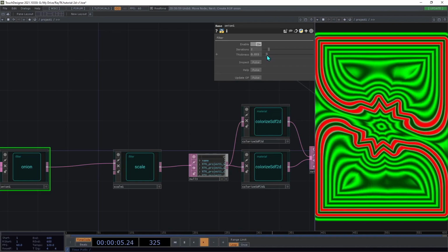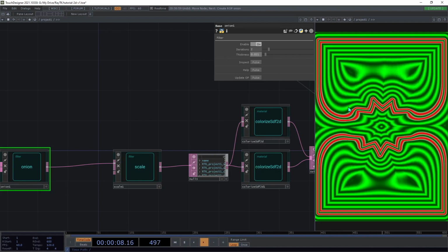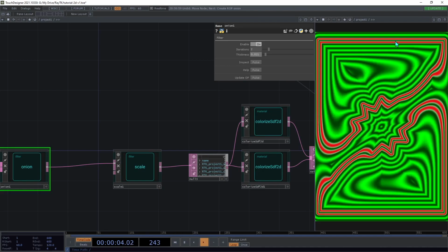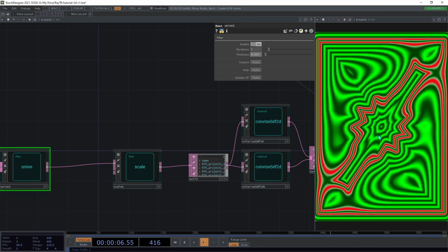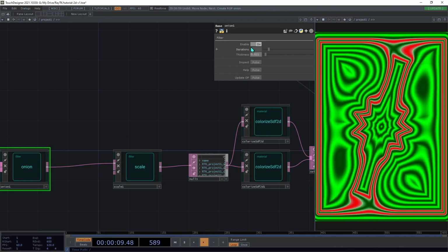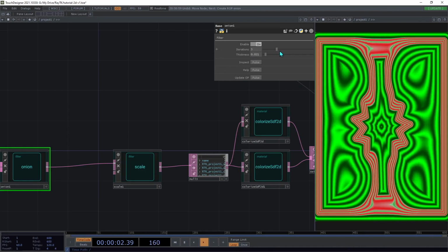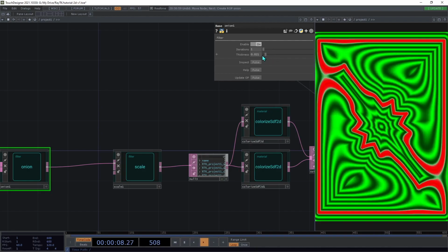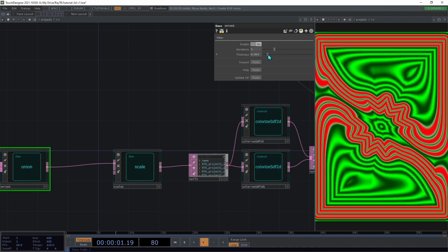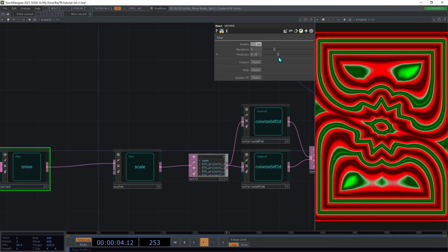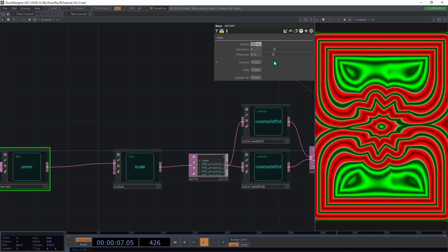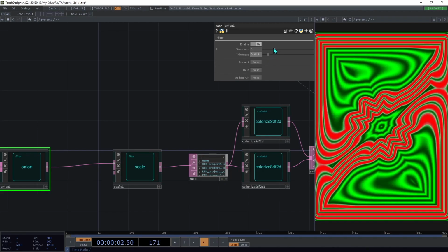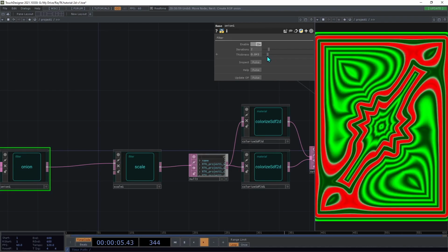So if you increase this thickness down there, you can see now it's producing a second shell. What it's doing is converting it to that hollow shell, and then it's converting the edges of that hollow shell to hollow edges of hollow shells, and so on. You can bump that up to different values. If you get high enough, or if the edges are close enough together, they'll merge together and be hard to see the difference between them, but you can play around with the thickness setting on that and the number of divisions that you're applying here.